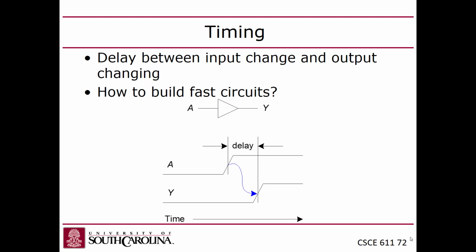Okay, so what is the problem? Why is that important? Because you've got capacitance, and the wires that make up the circuits, connecting the sources and drains and also the gates, all have resistance. Anytime you have resistance and capacitance, you end up with a time constant.